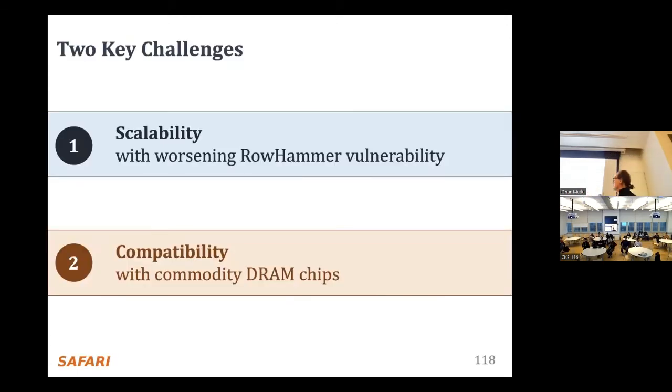So one of the things that we wanted was a solution that scales as RowHammer scales. For example, if you can induce a bit flip after only 10 hammers, can your solution be good in terms of performance? That's a very tough thing, because benign applications, not attacks, real applications, actually access rows hundreds of times within a refresh interval, some of them. Now the benign application itself becomes an attack, right? So can you actually handle that gracefully with low performance overhead and efficiency overhead? And then the other thing was, can you actually not change DRAM at all? Can you do this purely in the memory controller?